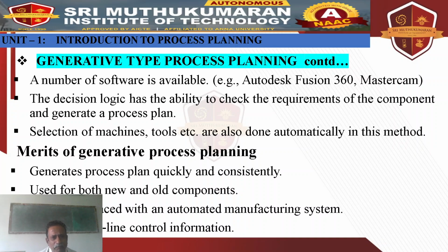For generative process planning, there are many software packages available. Some examples are Autodesk Fusion 360, Mastercam, etc. As I told, the decision logic has the ability to check the requirements of the component and generate a process plan. Selection of machines, tools, and all are done automatically in this method. So, merits of generative process planning: it generates process plans quickly and consistently. It can be used for both new components and old components. It can also be interfaced to the automated manufacturing system. It provides online control information.